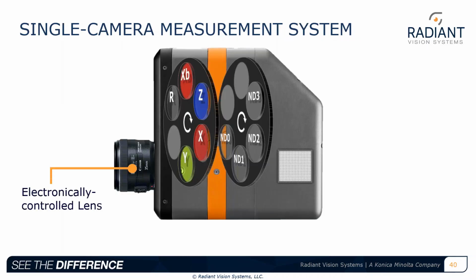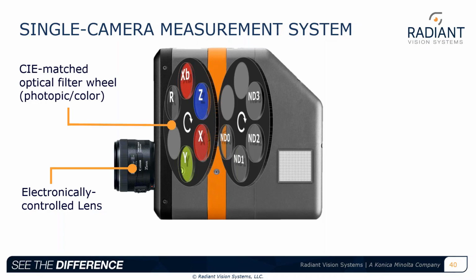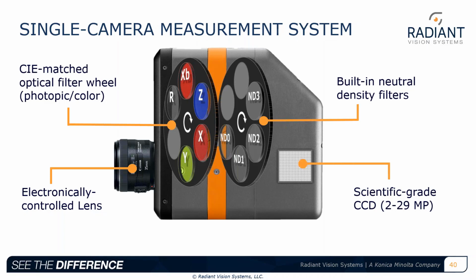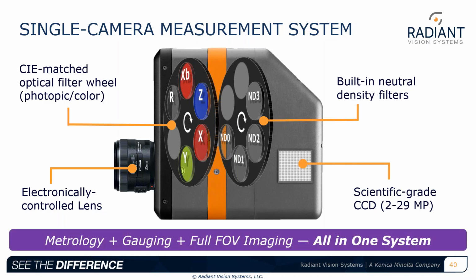And the system that we generally see being used today is the I-Series from Radiant Vision Systems. So this is a tri-stimulus-based imaging colorimeter with varying different resolutions. Radiant offers solutions from 2 to 29 megapixels. We have a 4-filter based system platform with a secondary filter wheel built in for neutral density filters, which is perfect for head-up displays because head-up displays are being driven at extremely large luminance outputs, which means saturation to the sensor is possible. So by incorporating neutral density filters into the measurement platform, we can adjust the filters based on the light distribution of the head-up display itself.